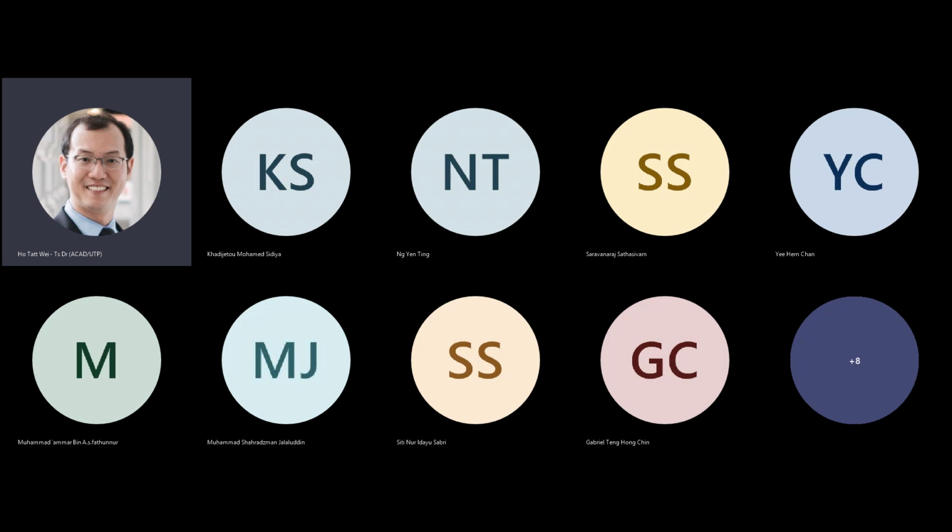Now, what we tend to do in semiconductor devices is we want to control the current by using voltage. If you look at the silicon device here, the number of free electrons is really not that much. It's nowhere near as much as the metal here. So we play a little trick. We insert impurities in the silicon. That's why we start with very pure silicon, a semiconductor lattice. That's why it's got a mirror-like finish, right?